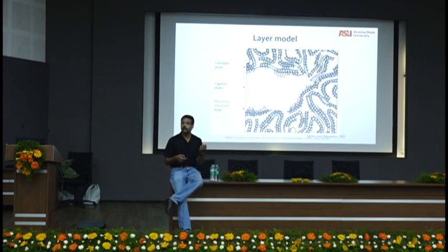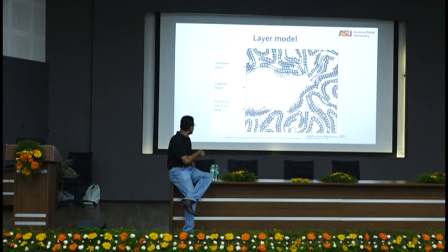That water is called adsorbed water, which is held on the surfaces by van der Waals forces. And then inside this whole big pore, that's your capillary pore, very large capillary pore, right? So when water drains, and this model has a lot of implications in how properties of concrete develop.